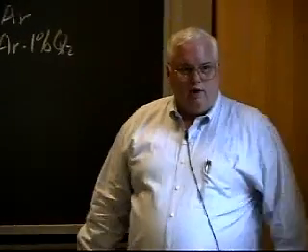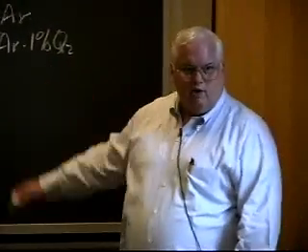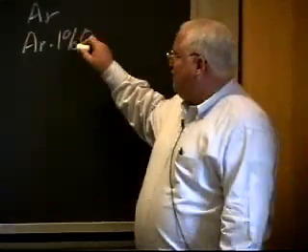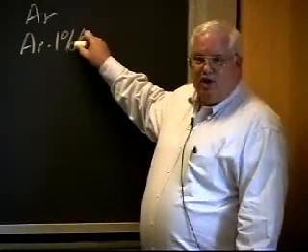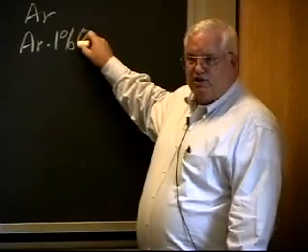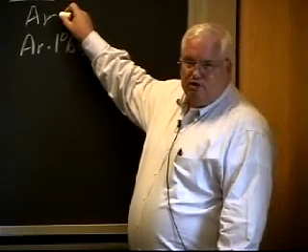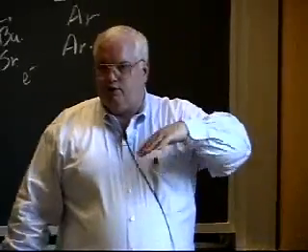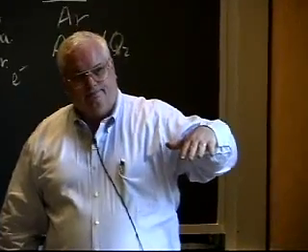If you've ever been to Electric Boat, where they weld a lot of nickel-based alloys, Inconels and Monels and stuff, they use this. It's great if you got a single-pass weld, but if you got a heavy section and a multi-pass weld, sometimes you're better with this. The problem with this is those non-uniform weld beads sometimes lead to lack of fusion defects.